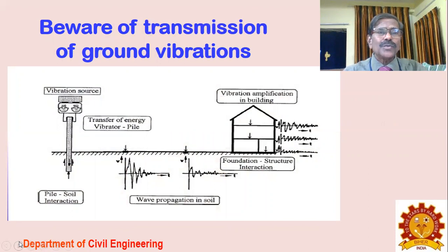But be careful when you transmit the ground vibration, the nearby structures also get vibrated. So foundation and structure interactions are being monitored continuously for the vibratory sources of the piles. Sometimes if a structure is very weak, it can cause cracks in the building, because if it is a very brittle structure like mud wall construction or a brick wall construction with poor mortar, then brittle failure can be induced because of the vibration generated by the vibrator Vibro-floats.